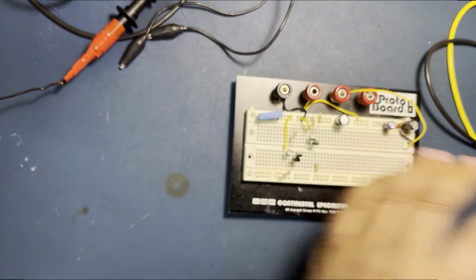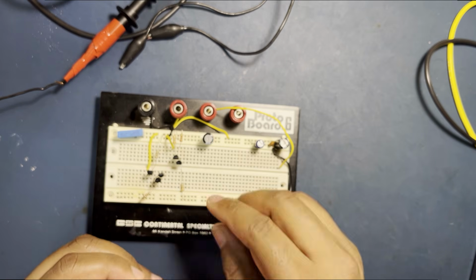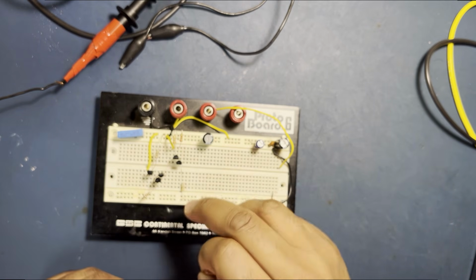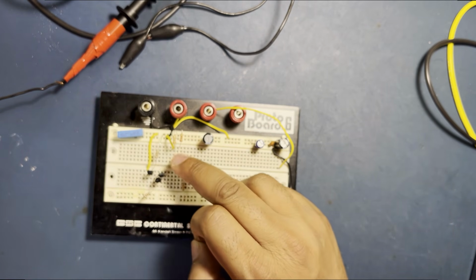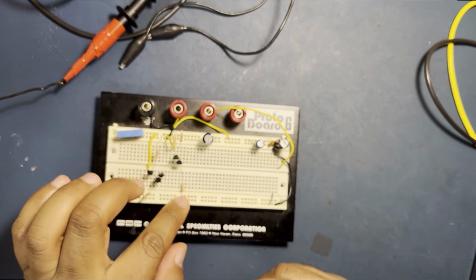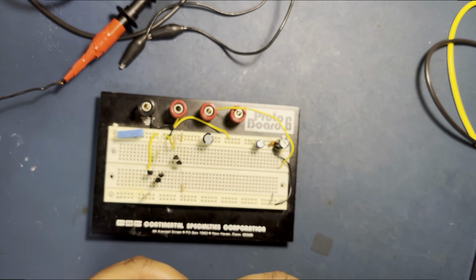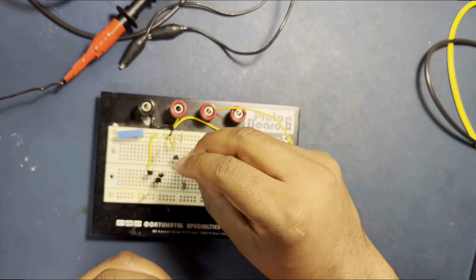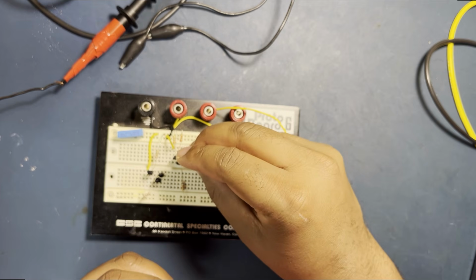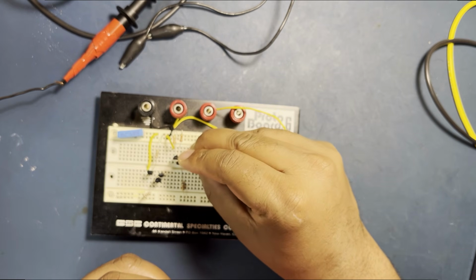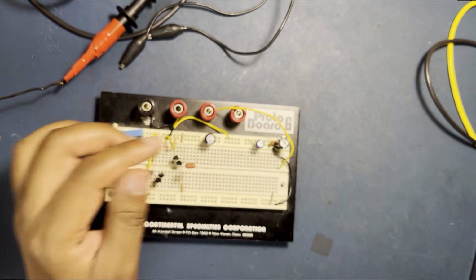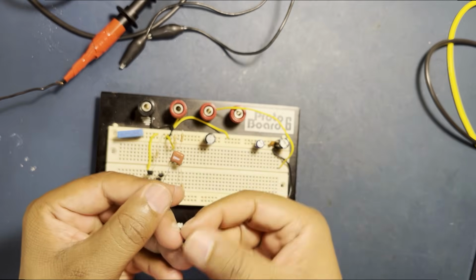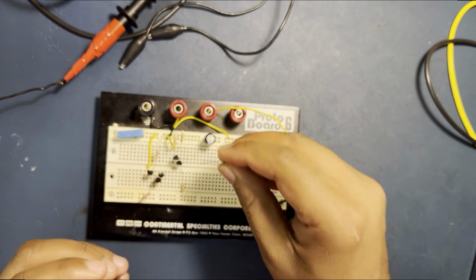So here's my circuit real quick to show you. So here's my two back-to-back connected PNP transistors that are going to generate the current. That's the 6.8K resistor. I'm going to measure all the values in a second. I'll just show you. So that will be connected to this guy here, and then it's going to come here. And the other side, now you're supposed to trim these long legs, but this is low frequency that we're using.